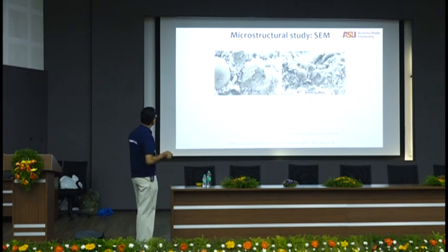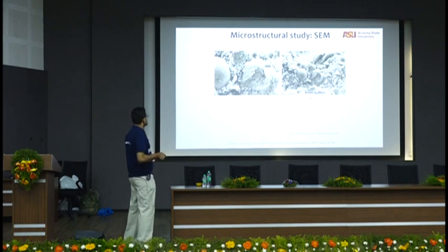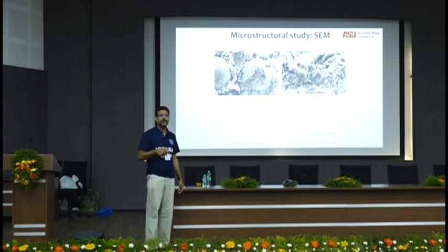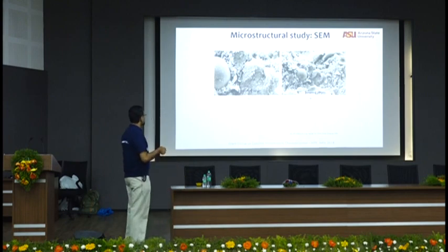Okay, so here is a secondary mode SEM of a certain sample. You can tell what these things are, right? Has to be fly ash. If you see something spherical in concrete and you know you've put in fly ash, there has to be fly ash. There is no other way. That can be something else. And then you can have a mass of all the other different things. And like I said, here's a scale bar. That's 10 microns. That's 20 microns.